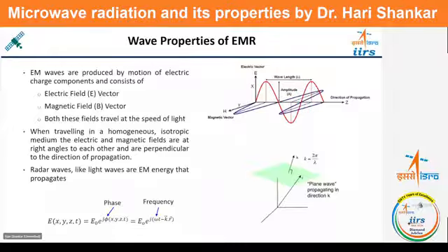But these microwave remote sensing images can see in 1 year how much motion happened, let us say 1 centimeter, 2 centimeter, so they can catch it very easily. So you can say a millimeter scale movement can be depicted with the help of these phase images. So that's what I'm saying. These phase images are very sensitive with respect to the motion.